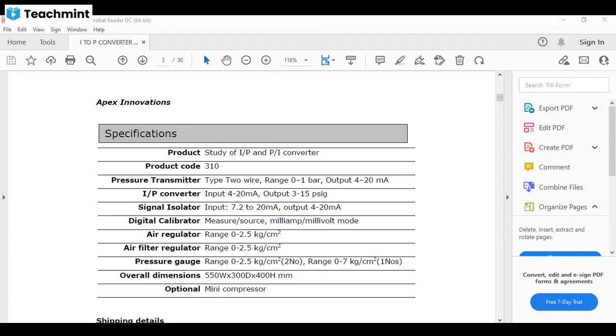The pivot is as in a jewel bearing, pivoted in a jewel bearing, as in the PMMC and moving iron type instruments. The pivot is connected through the flapper nozzle, and it is pivoted so that it can rotate or move freely, up and down. A magnetic material is attached to the other end of the flapper, and it is kept near the electromagnet, and the magnet is activated.